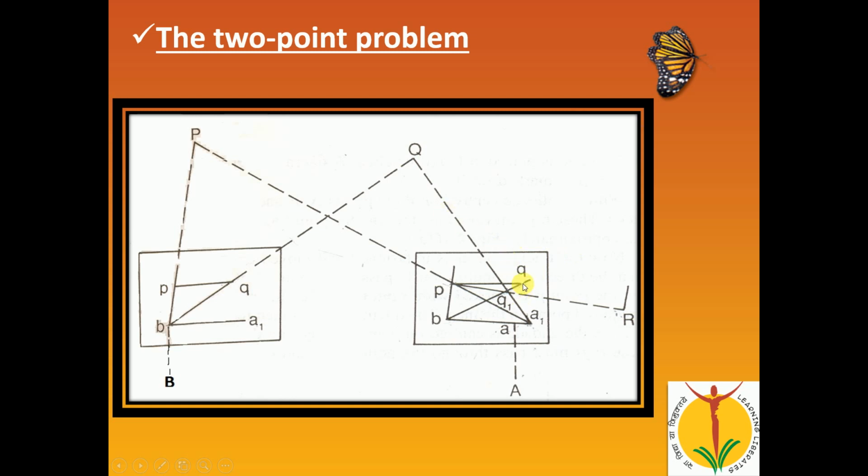But here you can see that the line, with the alidade touching point A and bisecting the ranging rod at Q on the ground, is not passing through the point we have marked on the plane table as a small q. So there is some error here. We have to do one thing: place the alidade touching point P and bisecting that point Q1.